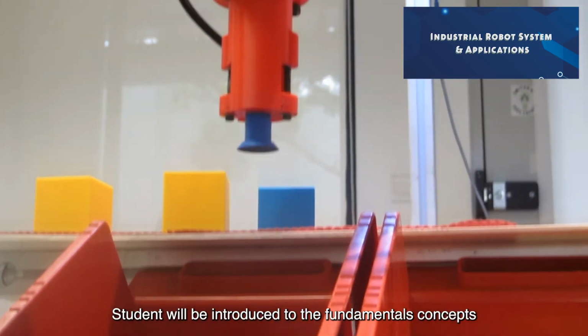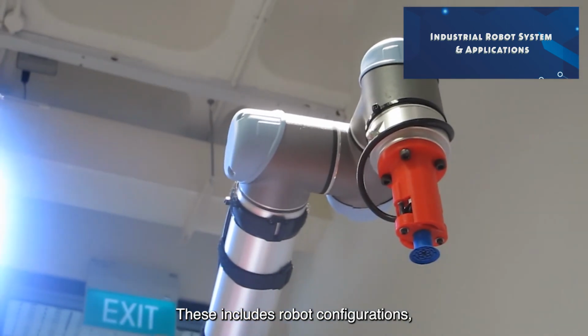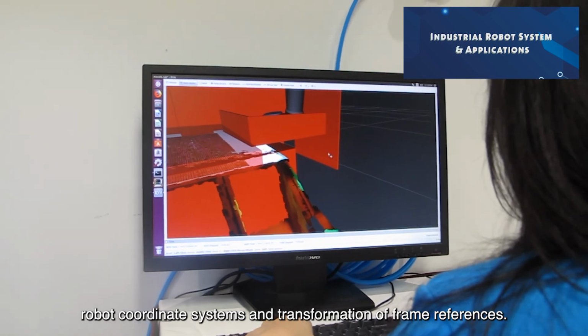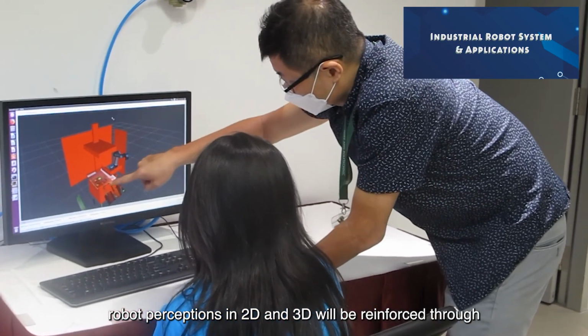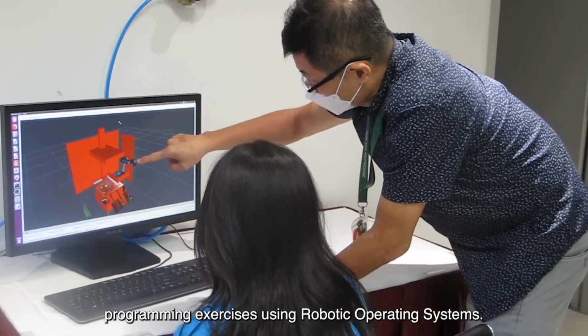Students will be introduced to fundamental concepts of industrial robot arms. These include robot configurations, robot coordinate systems, and transformations of frame references. To complement robot operation, robot perception in 2D and 3D will be reinforced through programming exercises using robot operating systems.